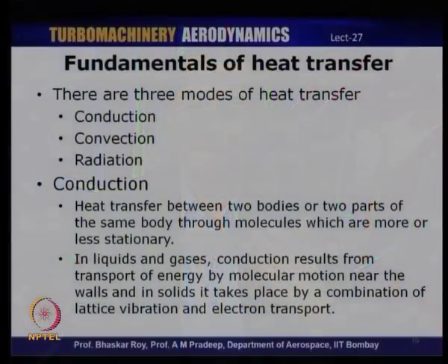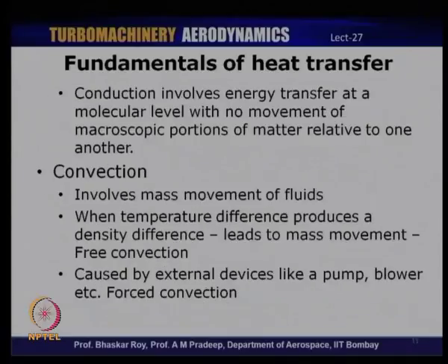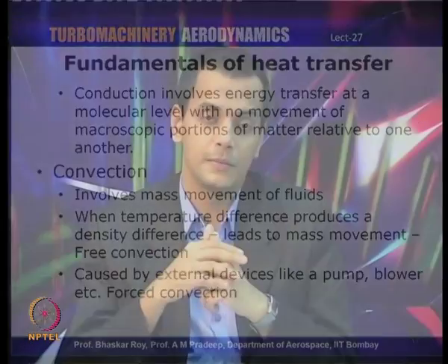In the case of gases and liquids, conduction basically results from transport of energy by molecular motion near the walls, and in solids it takes place by a combination of lattice vibration and electron transport. Conduction, as I mentioned, is energy transfer at a molecular level. There is no mass movement or macroscopic movement of matter relative to one another.